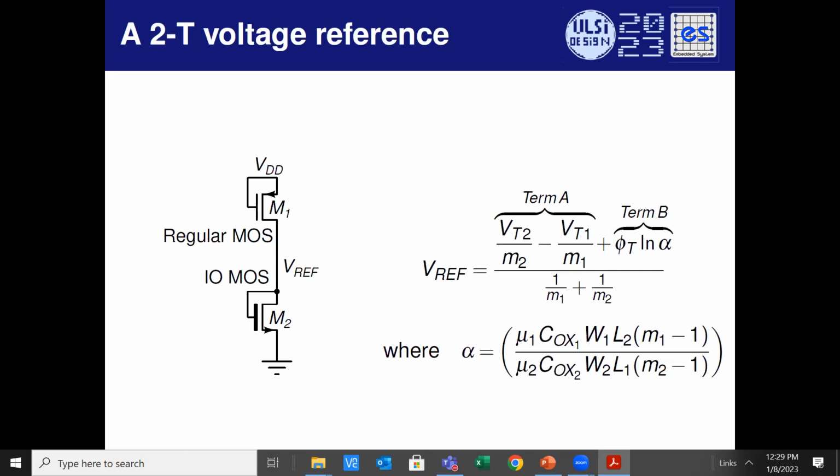Hi, sir. What about the PSRR? What about the PSRR of this architecture? PSRR is bad. PSRR is just one transistor, yeah, 1/GM is there. So if there's only one device, then you basically get PSRR worth one device. Okay.